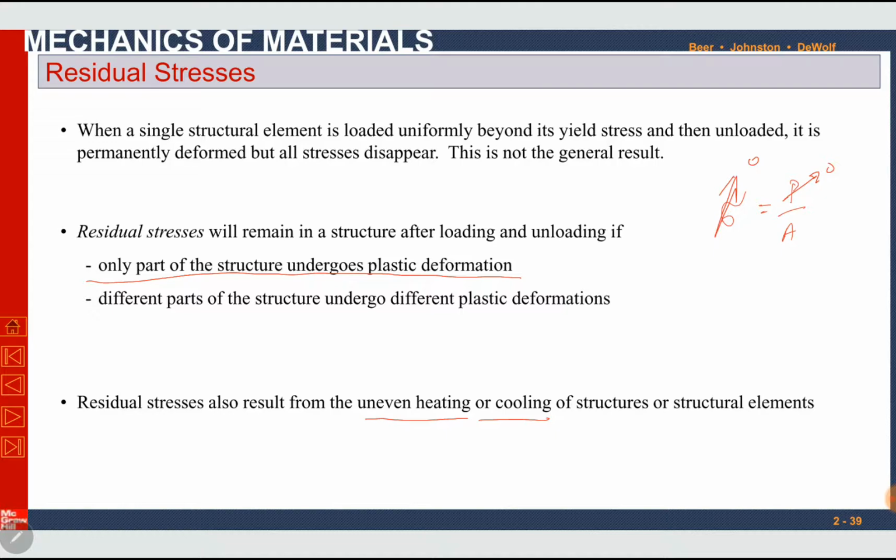Residual stresses may cause failures or may cause a decrease in the performance of structures. So it is always recommended not to load a structure beyond its yield strength, because whenever you load a structure beyond its yield strength, there will be permanent deformation in the structure, and after unloading, that permanent deformation cannot be restored and the material cannot come back to its original position. So there will be some permanent strain and permanent stresses in the material, which are called residual strains and residual stresses. This was the last topic of this chapter.